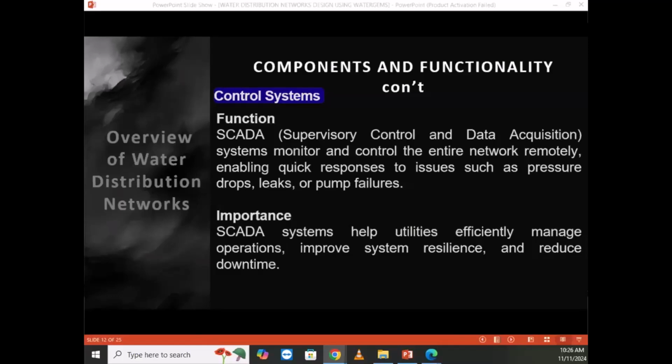The phone doesn't have precision. I can take a coordinate here, but when I put it in the model, it goes to the other road. So my pipe will not pass here; it will pass to the other side. By modeling, I'm modeling things on the other side while I have to pass my pipe here. You see the convenience. So by taking coordinates, you have at least to have a device which will help you to be realistic.